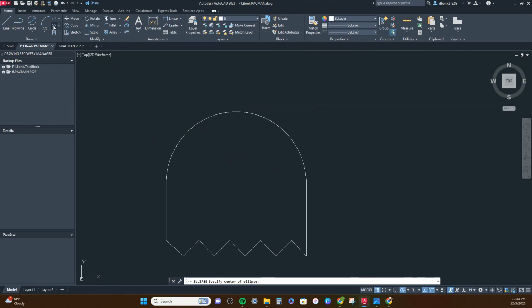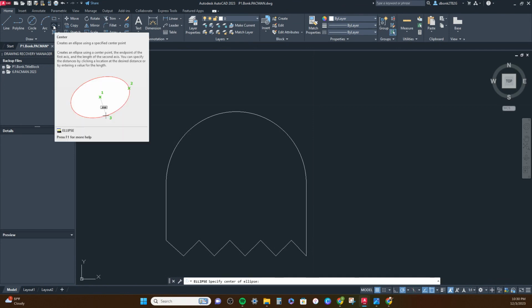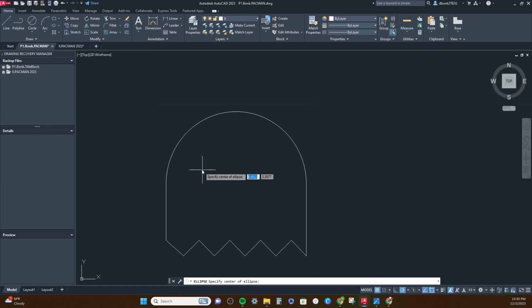What you're going to do is use the ellipse tool. Sorry, the end of this is funny with that funky ghost, but it's a 32nd of an inch, and if you get it right, it'll work out evenly. With the ellipse, you pull the height of the ellipse, and you're going to pull half the height, and it's going to double it. So if you play around with this tool, you'll get used to it. You pull the height, you pull the width. If I click the tool again, and I hover over and get the center point for that,